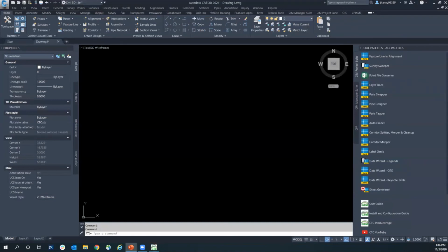One question: how do you draw a closed feature line without it popping up a warning requiring an elevation? Doesn't the command to close the feature line imply you are using the beginning elevation? Tricky question there, because the answer is yes and no. You might have to put a little space in, or connect it and do one of those, not insert PI, but one of those elevation points and put it on to get that to come through the way that you think it should.